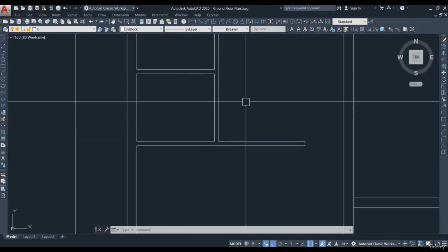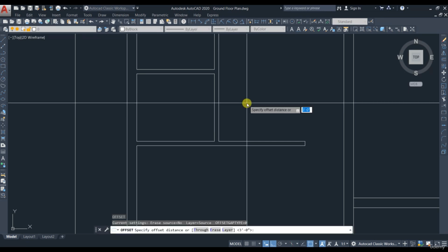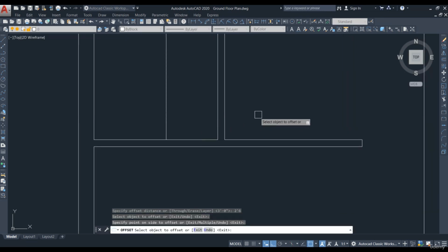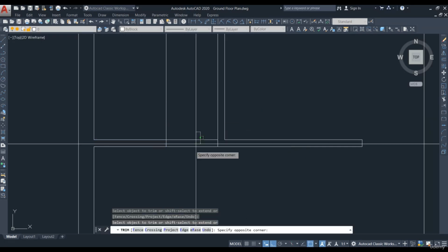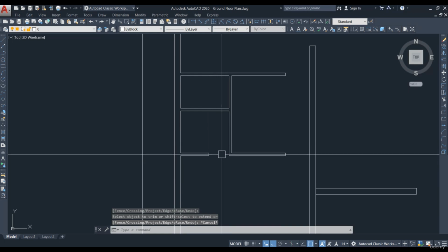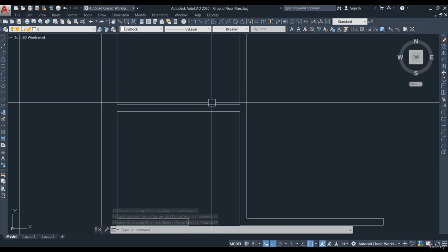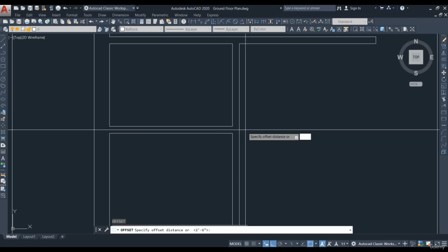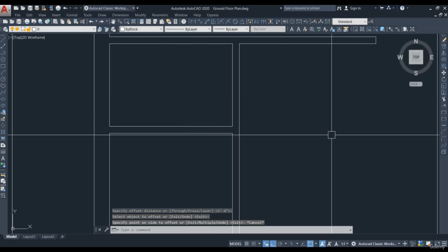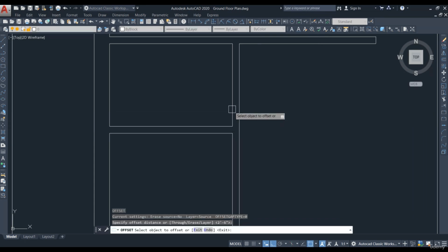And for this one we'll have the door open 2 feet 6 inches. So for this area and all, a 2 feet 6 inches door is fine. Trim, we'll provide the door over here, and then store we can just leave it open. Offset 2 feet 6 inches, offset 2 feet 6 inches, trim, extend.